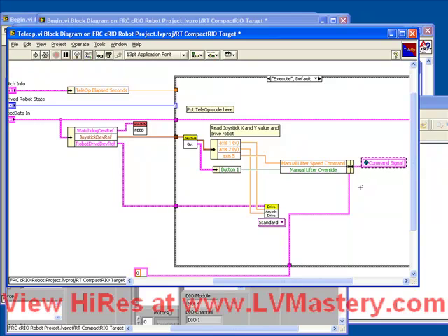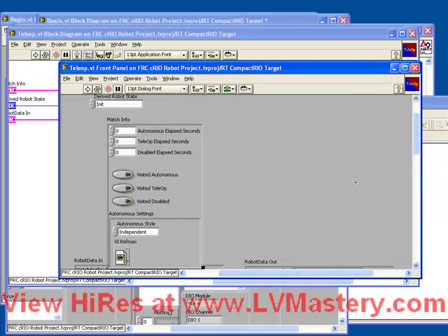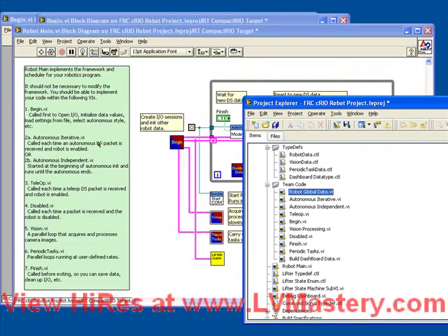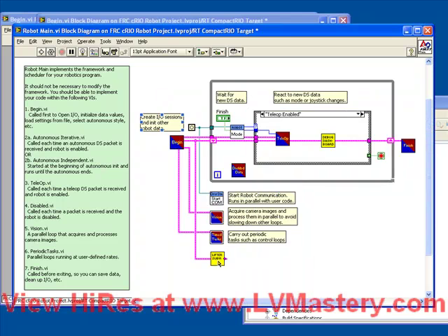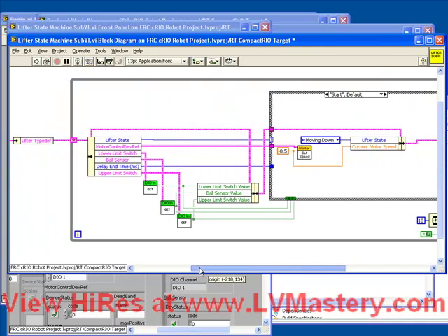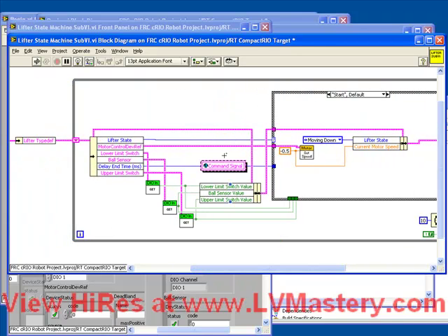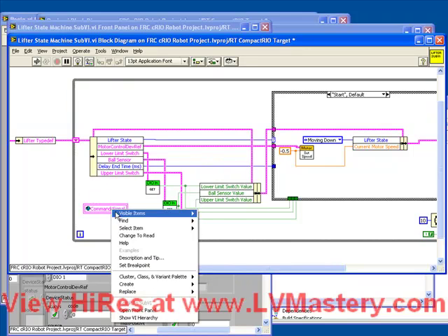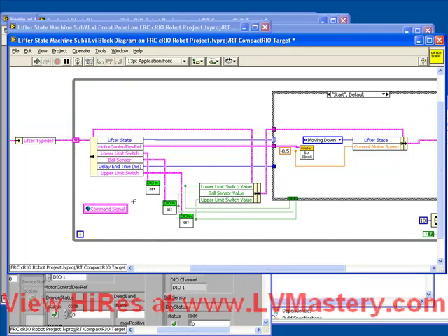So what we need to do now is read this global in our mechanical lifter and do the appropriate action. So let's just copy that global variable while we're here. Save and close our global data, open up our lifter sub-VI, go to the block diagram, and paste our global in. It's important to remember the global must be read inside the loop.